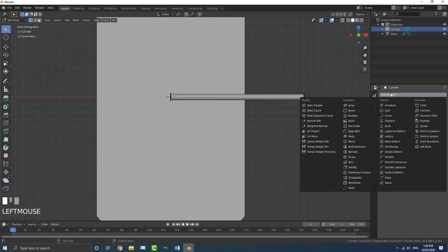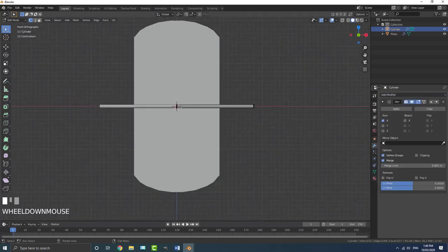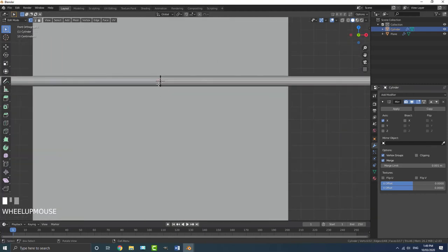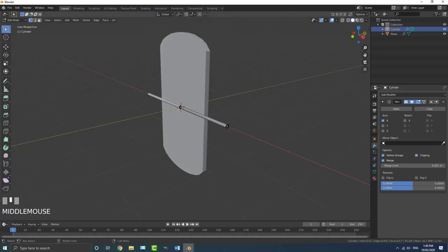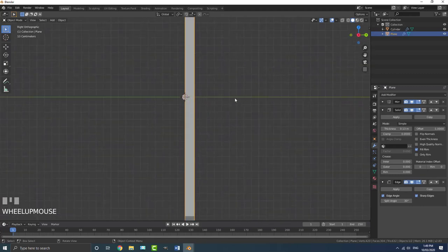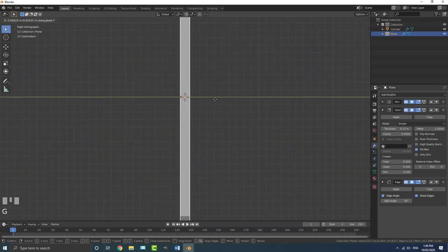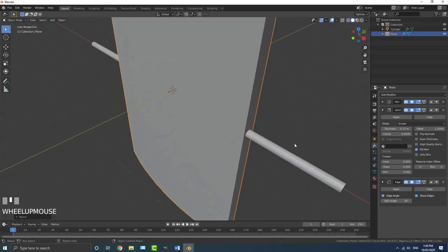And let's add in a mirror modifier. So we're going to go to a mirror modifier here, and we don't want clipping enabled. I think what we're going to do, okay, leave clipping enabled, so enable clipping here. And what we want to do is just tab out of edit mode quickly, grab this over here, and you just go G, Y, and just move it so it's right in the middle of our scene, so we don't see this here.